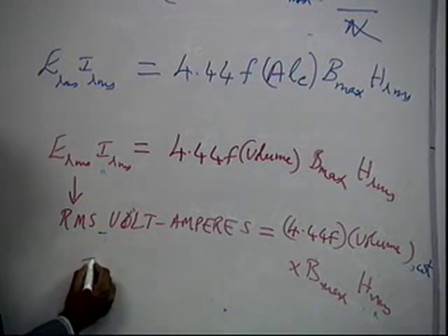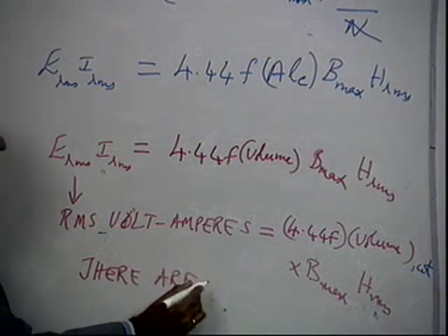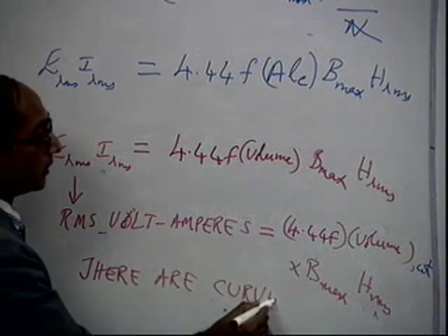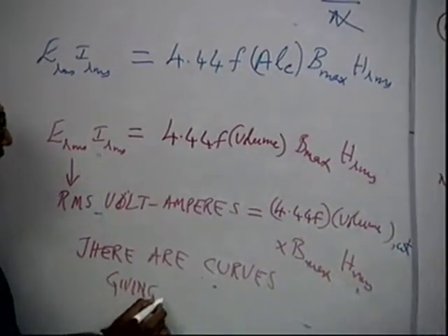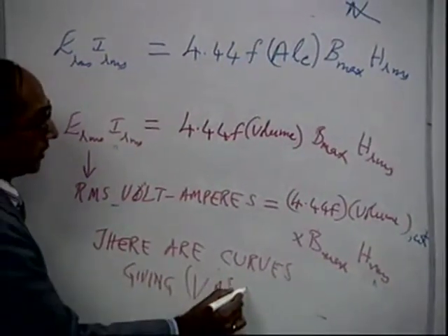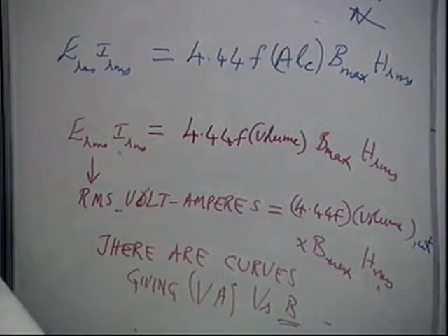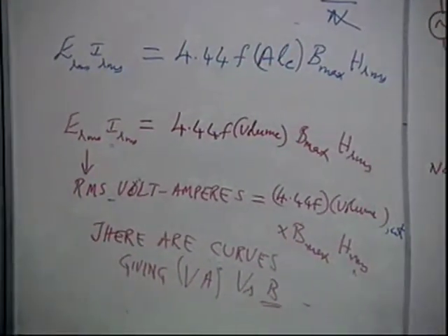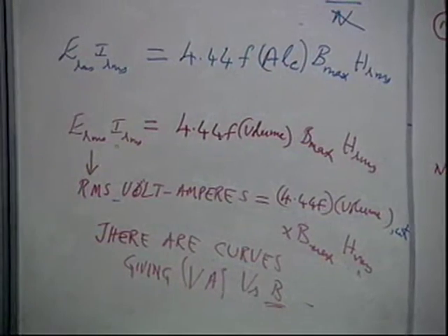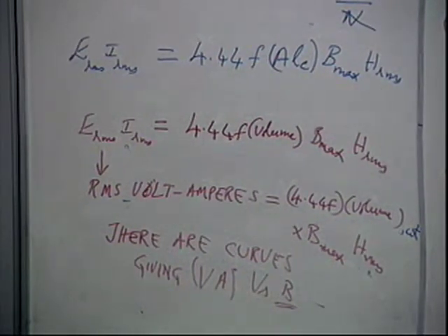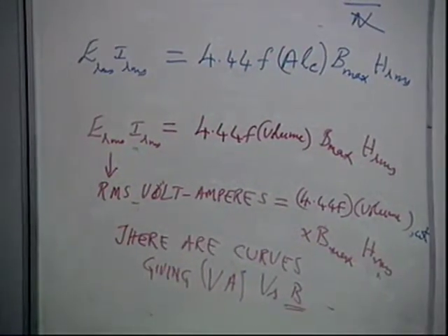So there are curves giving volt amperes versus B, operating at the given frequency. I will show you the RMS volt amperes for one of the materials here. These are called exciting RMS volt amperes.